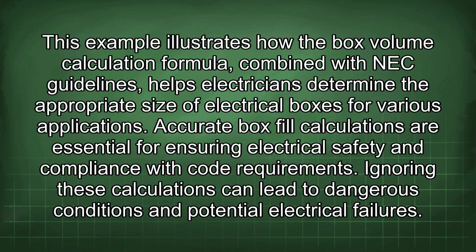This example illustrates how the box volume calculation formula combined with NEC guidelines helps electricians determine the appropriate size of electrical boxes for various applications. Accurate box fill calculations are essential for ensuring electrical safety and compliance with code requirements. Ignoring these calculations can lead to dangerous conditions and potential electrical failures.